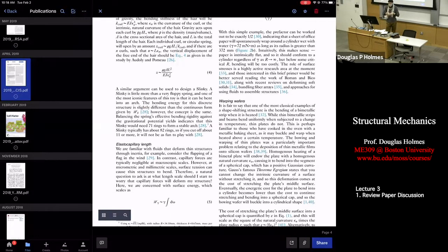if you want to make stuff on a really small scale, like lithography, for making computer chips, you kind of take a wafer, put a material on it, put a mask on it, shine light. Wherever the light touches, it makes that liquid film solid. Then you dip it in solvent, and you're left with whatever you made solid standing there. And that's how people make all the computer components.